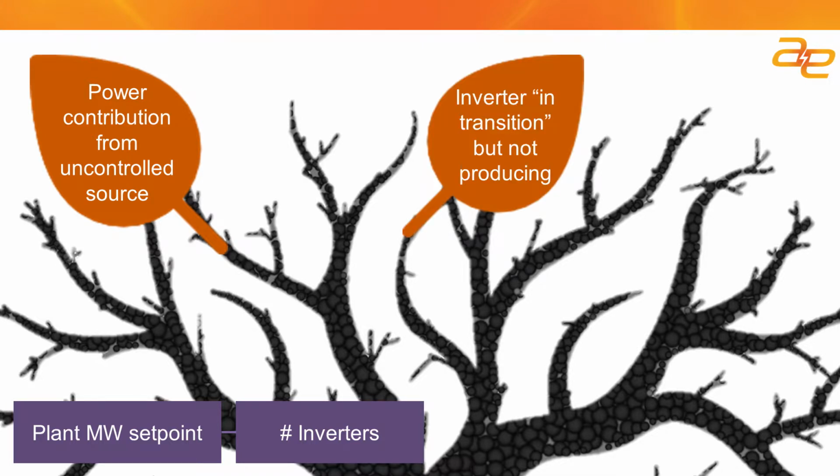The next fun topic with solar inverters is the requirement that the inverters, from the time they're given a command to start, wait 300 seconds before they actually start. There's a good reason for this time delay. If there's a distributed generation connected solar site and there are problems on the line, maybe there's a windstorm and trees are hitting the lines somewhere up or down the line, the stability of the line might be such that you don't want to reconnect the generation if there's a short disturbance.